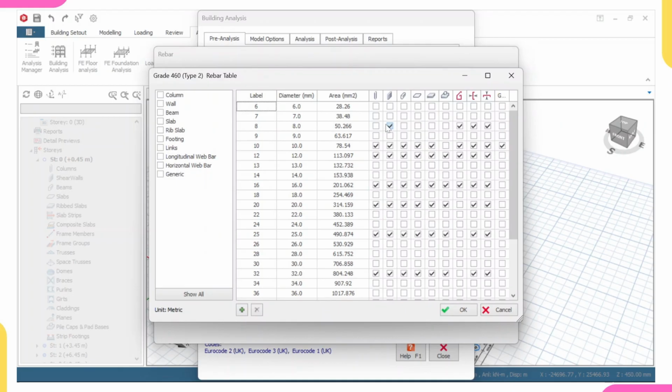So coming over to column, I would like my column to be this Y16. Then I would not like to check any other one again. If 4Y16 fails, it should give me 6Y16. I don't want Y20, because I know my client will not like Y20. So there's no need of me applying Y20, because I know that with this Y16, if it fails, it will just increase the number, maybe to 4, 6 or so.